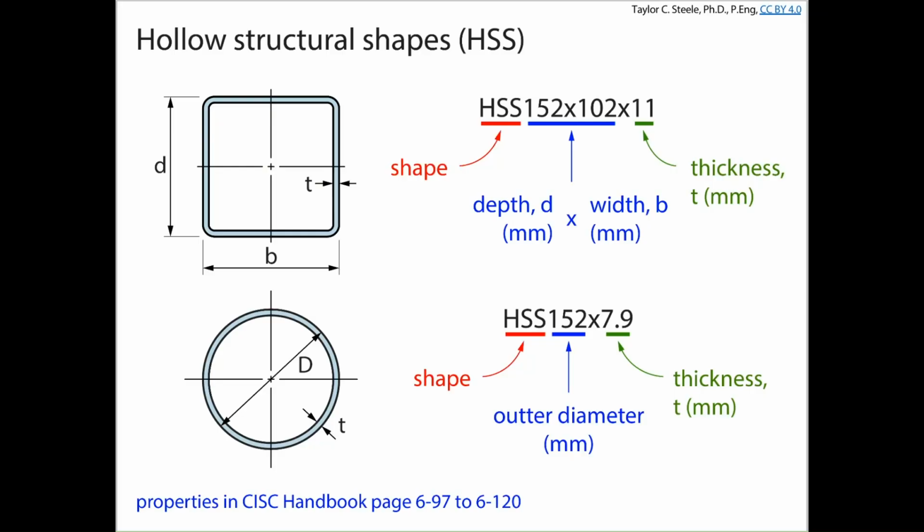And so when I pass this around, you're going to see this is about a ½ inch thick. And if you tried to measure the radius of the inside corner, it's also about ½ of an inch. We've got circles, same thing, but it's just diameter times thickness. And circles tend to be used a bit more in architectural applications than an HSS might be. HSS tend to be used as columns or braces, and then they end up getting tossed inside a wall so nobody can see them.